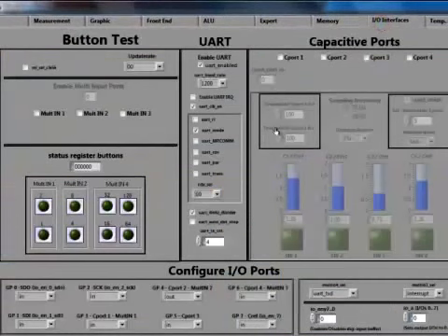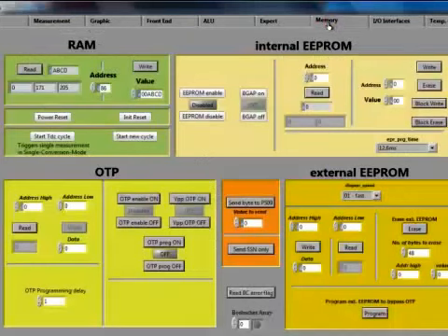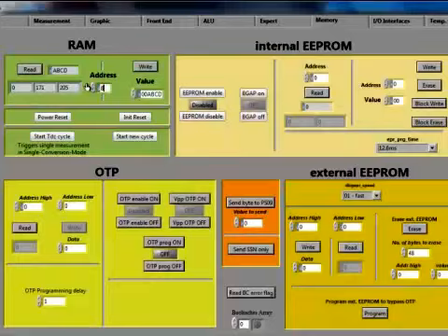Then select the UART trans option once and deselect it. This will generate the start transmission pulse and the 2 bytes are sent out in one go. You can recognize that the bytes have been transmitted by reading the UART register 80.